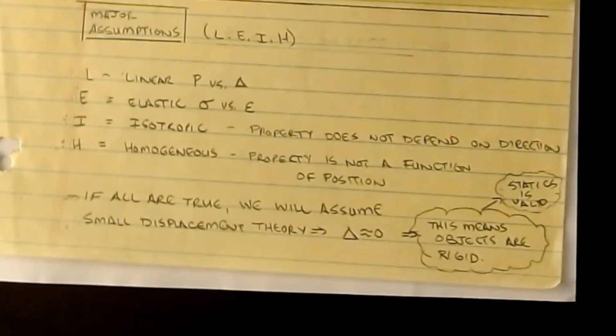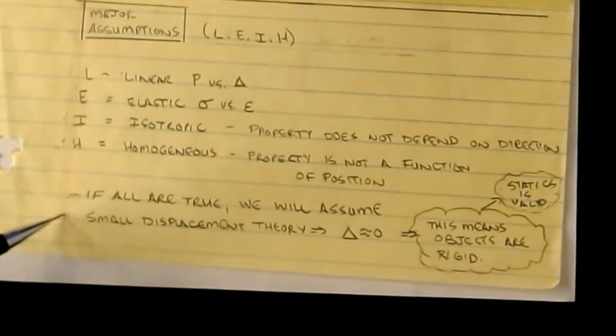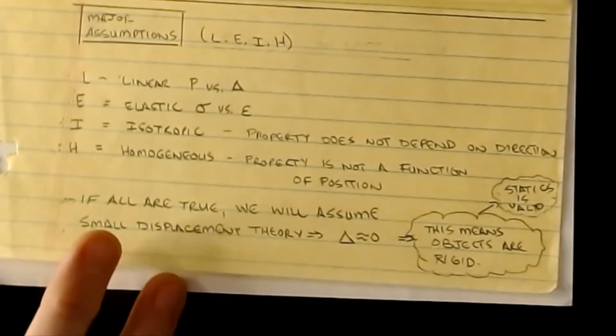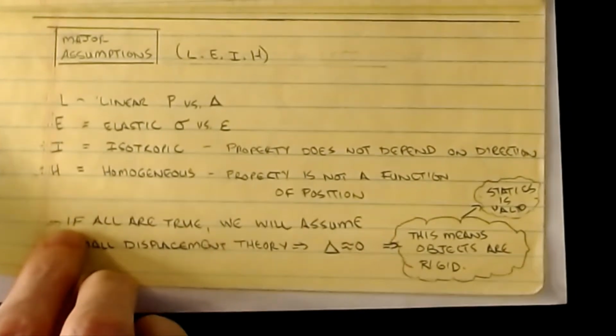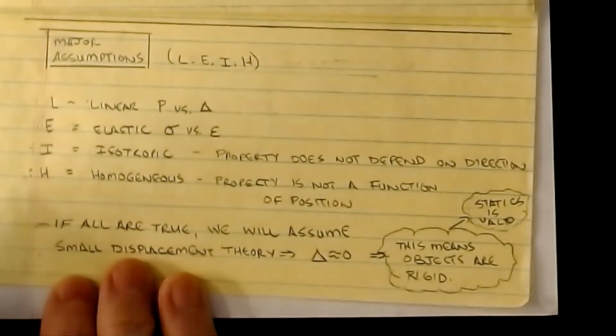And so for us, we can say our assumption of small displacement would be valid for that as well. A lot of design codes set prescriptions on maximum displacements allowed on members, recognizing what these dimensions usually are, and assuring that we hit that requirement for small displacements. That's a little bit of trivia behind the scenes of what they're trying to do. So those are some of our major assumptions that we're going to be dealing with.